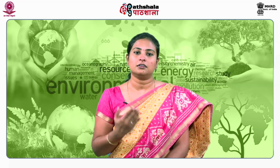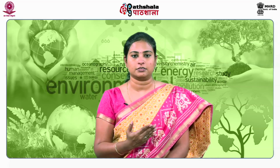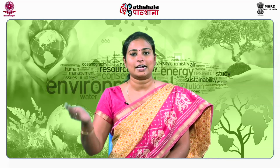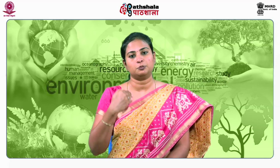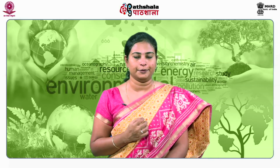This is again due to the attached microorganisms. The suspended microorganisms show more efficiency, which is clear in an activated sludge process compared to rotating biological contactors, because the microorganisms performing the degradation are only attached and are very small in number.